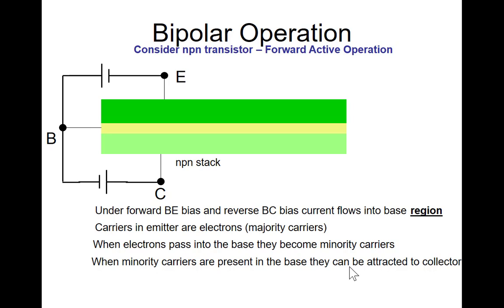We're not applying a positive and negative voltage to the base. You can think of this as ground if you want to for the purpose of this illustration. So I'm putting a negative voltage on the emitter and a positive voltage on the collector then. Good question, but I'm not providing two separate. If I connected these together, then we'd have a problem with Kirchhoff's voltage law around the loop, but I've not done that.